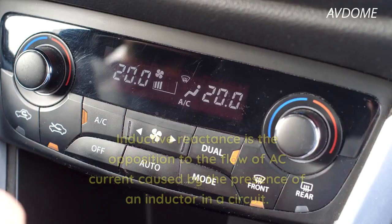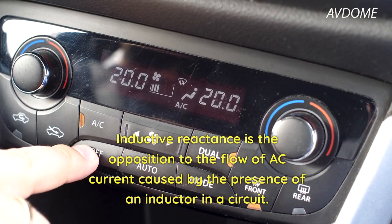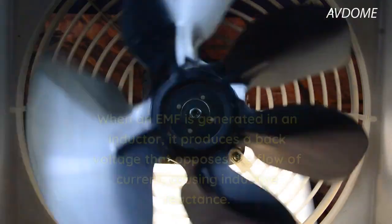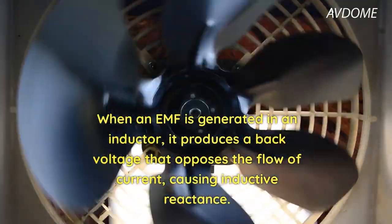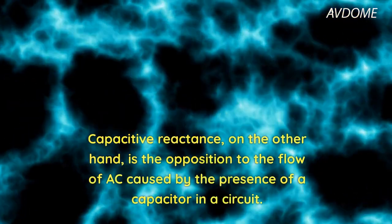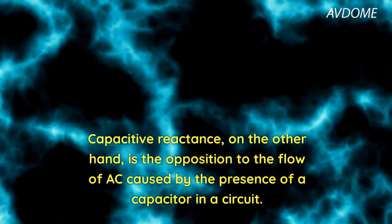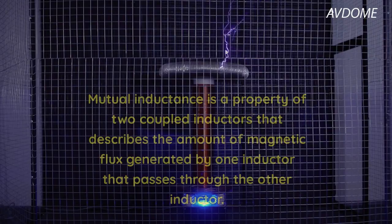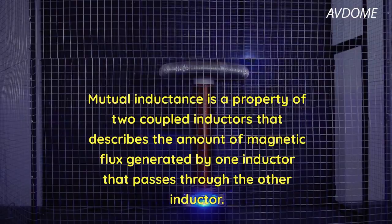It is A. Inductive reactance is the opposition to the flow of AC current caused by the presence of an inductor in a circuit. When an EMF is generated in an inductor, it produces a back voltage that opposes the flow of current, causing inductive reactance. Capacitive reactance, on the other hand, is the opposition to the flow of AC caused by the presence of a capacitor in a circuit. Mutual inductance is a property of two coupled inductors that describes the amount of magnetic flux generated by one inductor that passes through the other inductor.